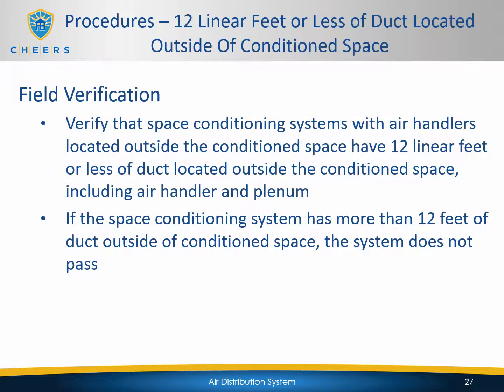Now, to verify 12 linear feet or less of duct located outside of conditioned space, you want to verify the space conditioning systems with air handlers located outside the conditioned space have 12 linear feet or less of duct located outside of the conditioned space. This is including the air handler and the plenum. You're just measuring the ducts and making sure that it's less than 12 linear feet. If the space conditioning system has more than 12 feet of duct outside of conditioned space, then the system does not pass.